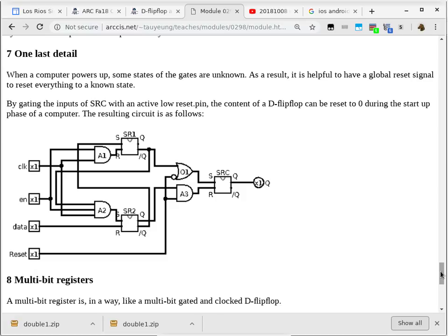That is independent of all the rest of the circuitry, because this circuitry is closer to the SR latch than all of the other circuitry, which basically means you can be clocking, you can be enabled or not enabled, the data can be a 0 or 1, nothing matters. As soon as reset goes from a 1 to a 0, the final SR latch, SR3, is going to switch to a 0. Why don't we need that?